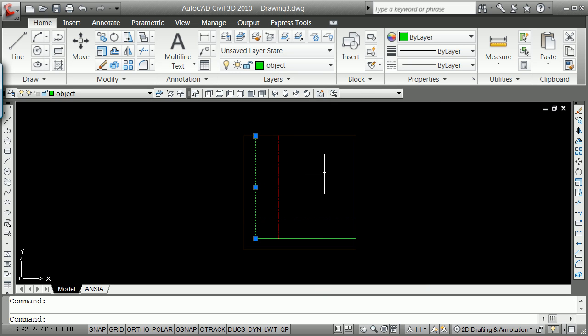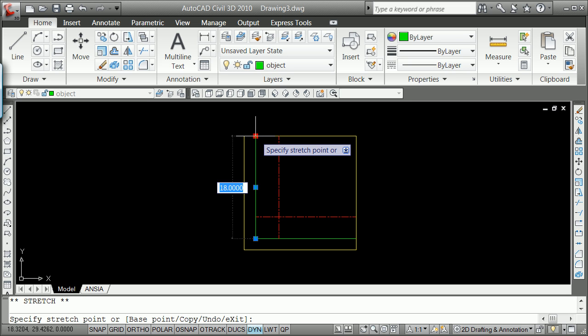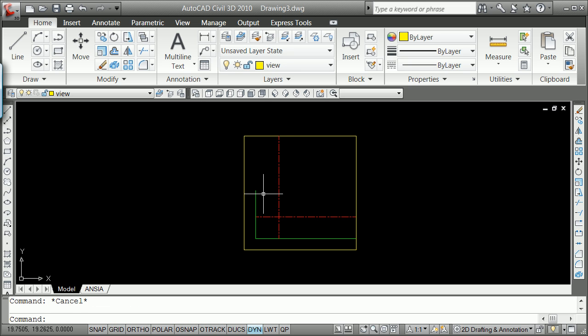So you can do the following. This strong line here, if you want to change its length, there's all kinds of different ways to do it. You can draw a circle and trim, but one way to do it is if you have left clicked on it. Now if you left click on the edge you want to change, instead of hitting spacebar, you're going to get a different input if, in fact, you've turned down the dynamic. So I did it again, left click, and I left click here. You see nothing looks that odd. We do that for modify. However, if I turn on the dynamic and I left click and I left click again, I get that input, and I can tab there and type in the length, 8.37, and hit return, hit escape, and I've changed my length. So that only works by turning the dynamic on.